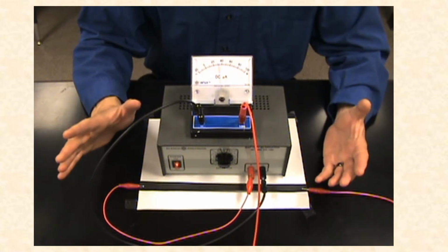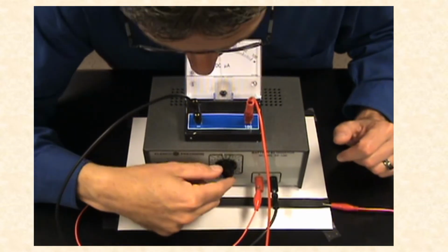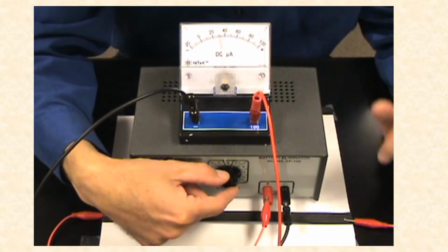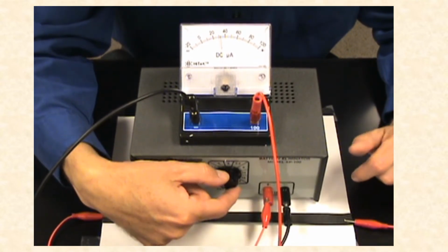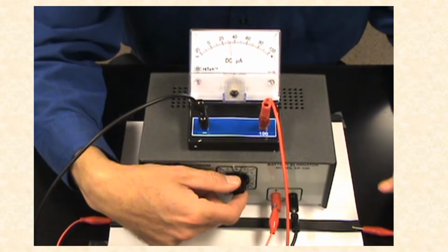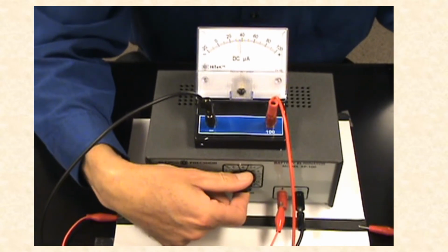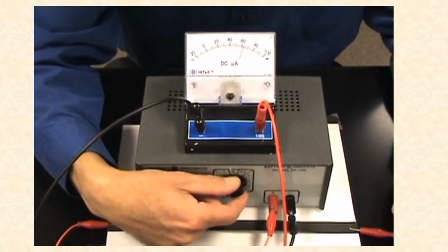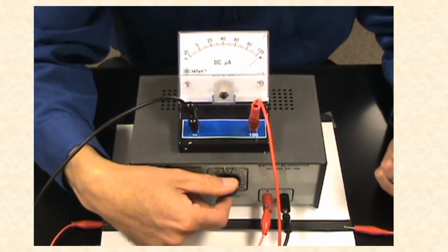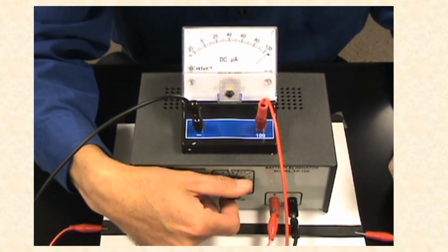So let's start by taking a look at the effect of voltage on current. You'll notice here, looking at the DMM, that we have a certain voltage and we have a certain current. Notice what happens as I increase the voltage. As I increase that voltage by turning the dial, I'm going to increase the electrical pressure across the ends of the circuit, therefore increasing the current. So here goes. Increasing that voltage, notice that the current increases as well. Okay, now we've pegged our meter, we've maxed out. All right, so we see there's a direct relationship between voltage and current.